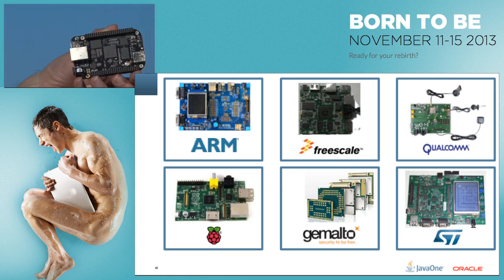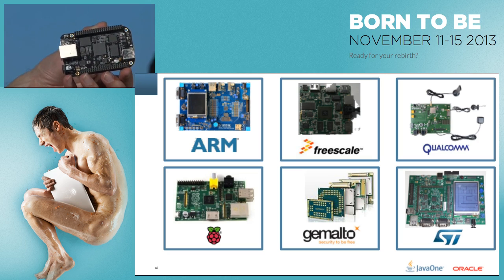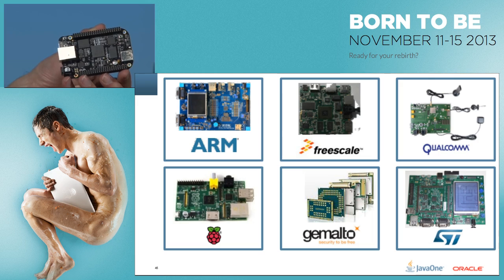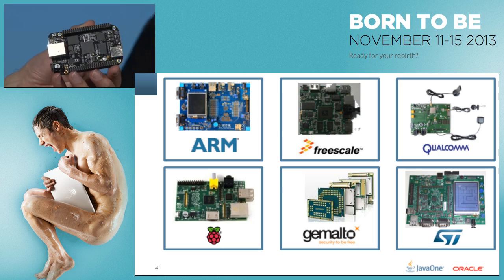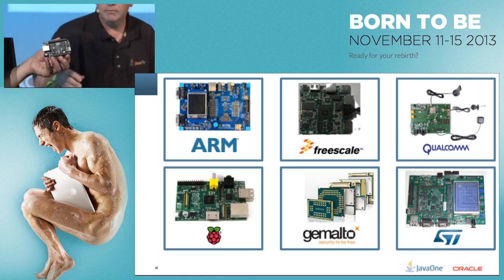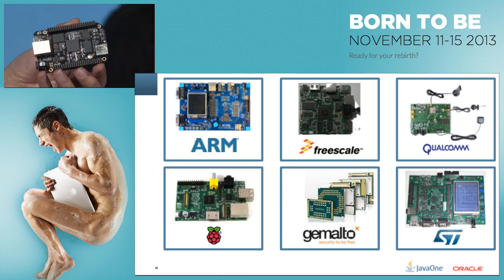But they also have a PandaBoard, which is a multi-core system. This one here has a Cortex A8 processor inside it, whereas the PandaBoard is a Cortex A9, and that's dual 1 gigahertz. This one here is, I think, 1 gigahertz and 512 megabytes of memory. So if it was me testing, I would choose this board over that board because it's 1 gig of memory, and it's just much easier to run with testing.